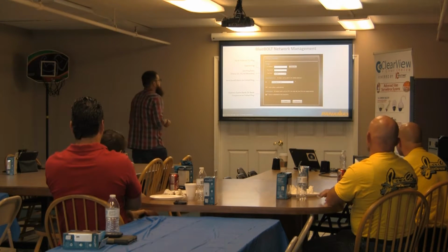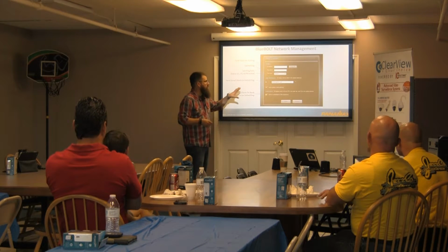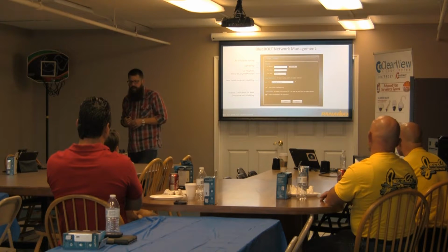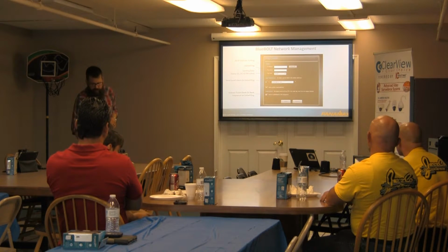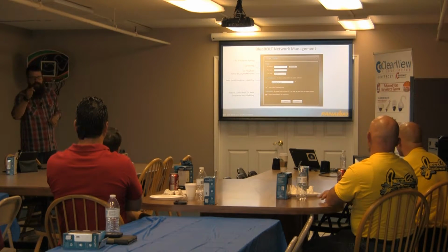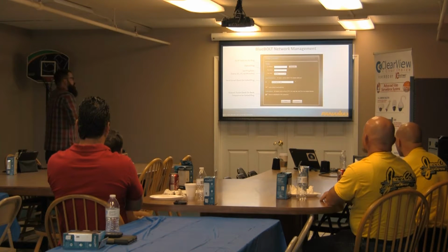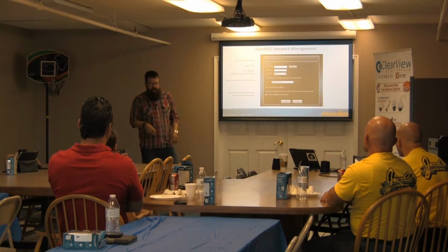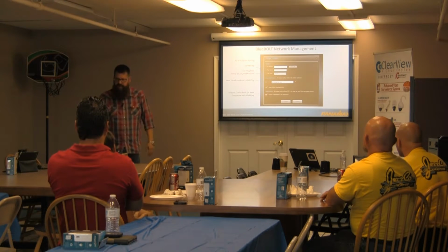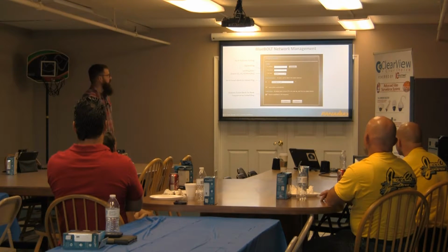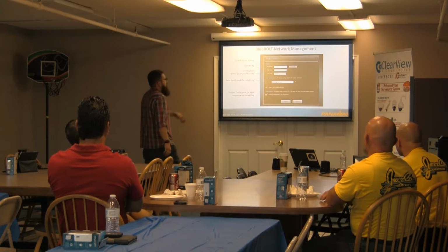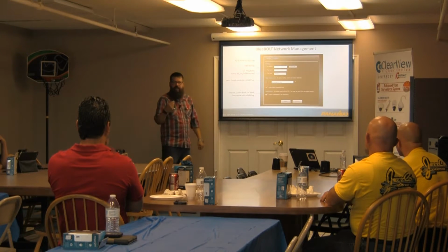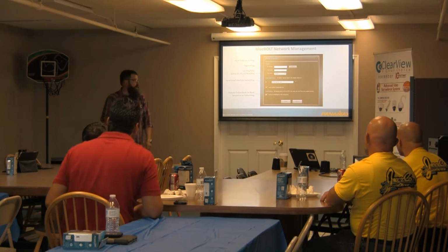And then network management. This is one of my favorite pieces, and we just added this feature to it. Inside of the Bluebolt software, we have the ability to constantly be pinging a network device. Say your Apple TVs, you've got them on the network and plugged in. Say I've got 2 Apple TVs, one in bank 7, one in bank 8. I type in the IP address of the Apple TV, and then you hit test IP just to make sure it's a valid IP address on your network.